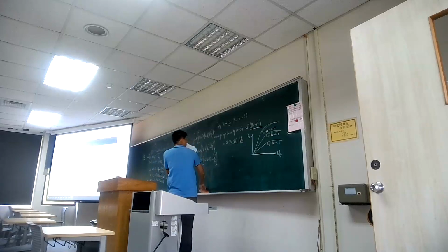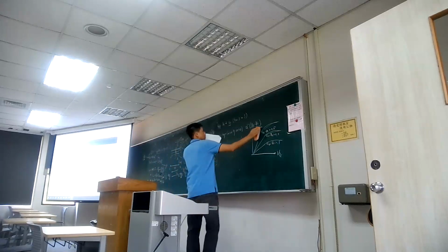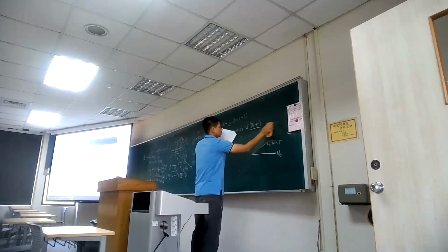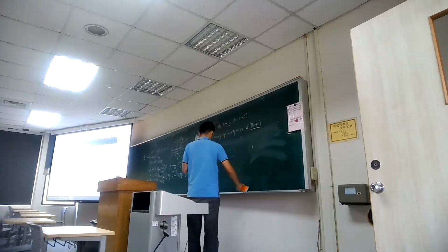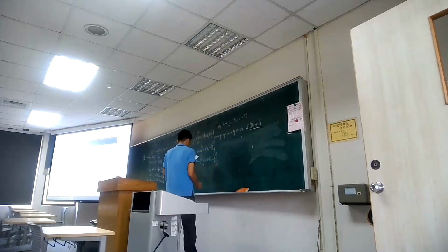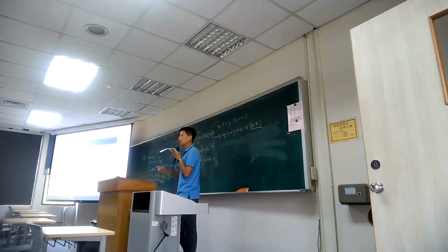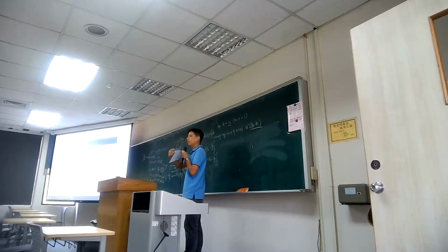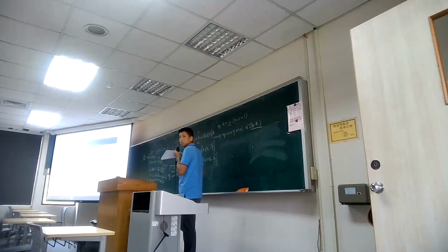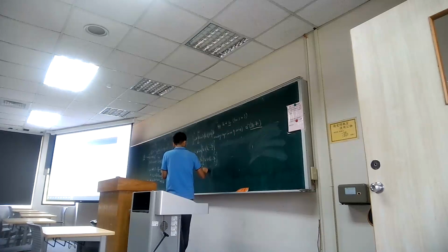For some simplification, typically you can rewrite the equations with a simplified model, as some people do in textbooks. Typically you can say W over L is the scaling factor. It tells you how large your metal gate is, and we call this the aspect ratio.